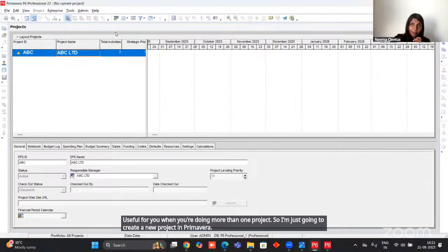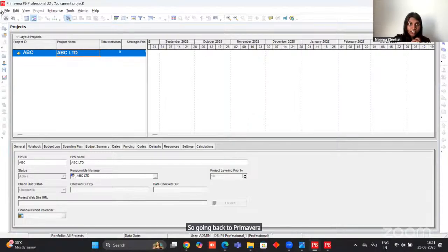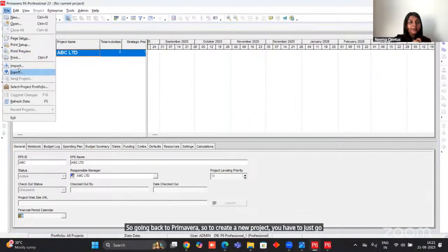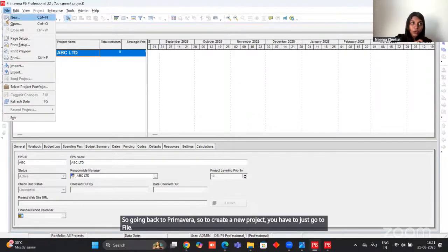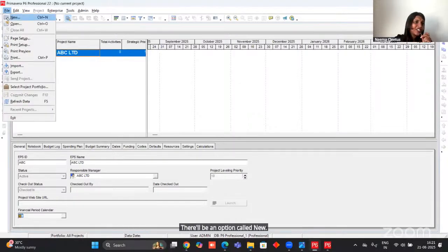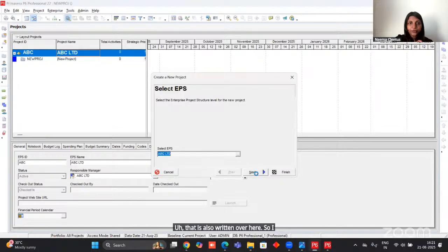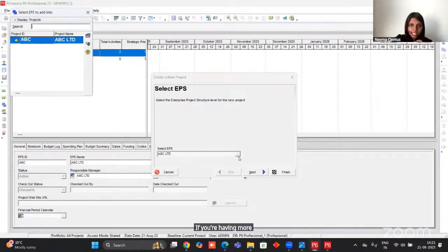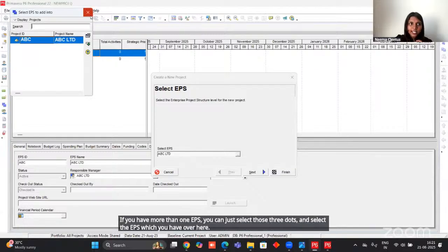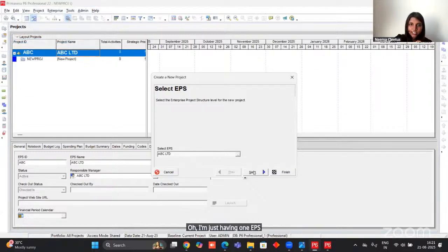So going back to Primavera, to create a new project, you have to just go to File. There will be an option called New. You can use the shortkeys also. That is also written over here. So I'm just selecting New. The first option will be to select the EPS. If you're having more than one EPS, you can just select the three dots and select the EPS which you have over here. Now I'm just having one EPS, already selected that.